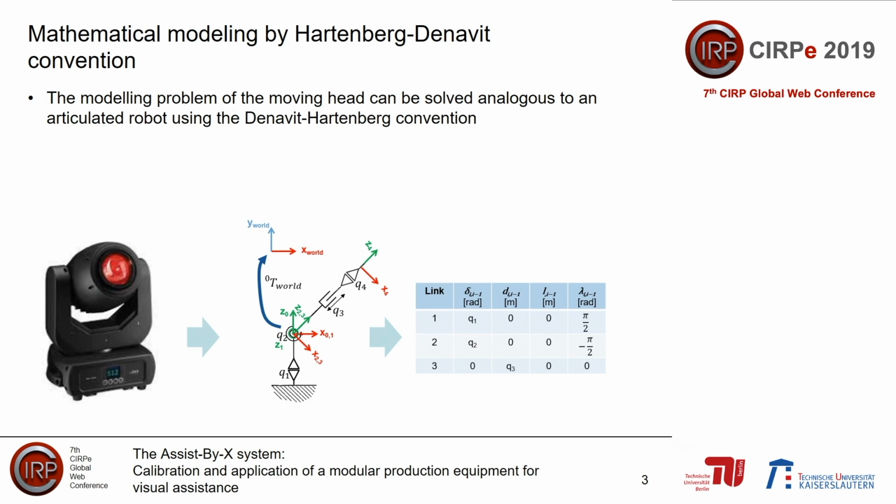Moreover, the moving head is not a cyber-physical system and cannot communicate with its environment, whereby it has to be equipped with a Raspberry Pi to meet the demands of an IoT scenario. The processing of the MQTT message into the device-specific commands is realized with the help of a Node-RED flow and is carried out with the other devices in a comparable way.